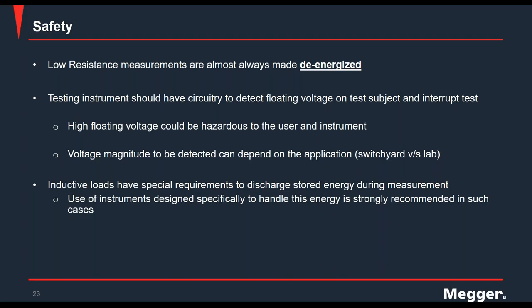And the voltage that has to be detected can depend on the application. Say, for example, if you're in a switch yard measuring resistance values on a circuit breaker versus measuring PCB resistance in a lab on a printed circuit board. So the next point is talking about inductive loads. Inductive loads have special requirements to discharge the stored energy during measurement, because of the inductive nature they store energy, and this stored energy has to be discharged. So it's very, very critical that instruments that are specifically designed to handle this energy are used in resistance measurements.